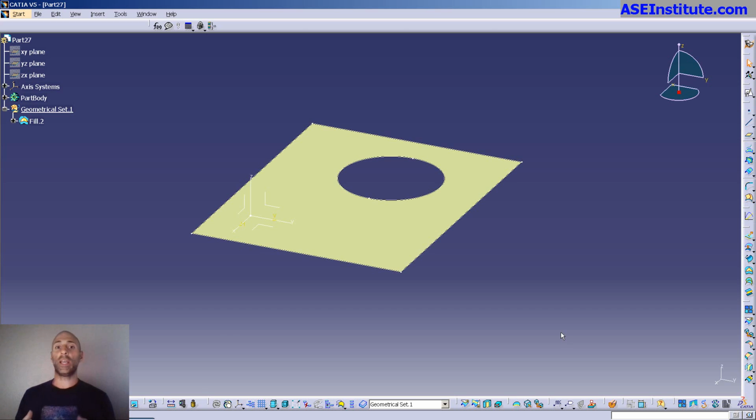If this were a split on a plane, as I just did here, I could potentially have three results: one to the outside, one to the inside, and one to the inside of that hole, depending on how the normal of the plane shifted. But in this case, there's only one possible result because the system knows that is an inner boundary.